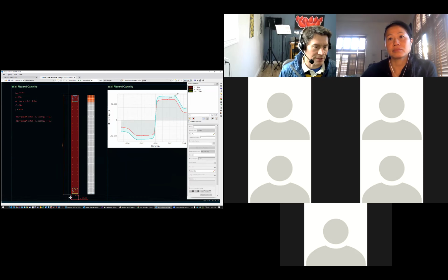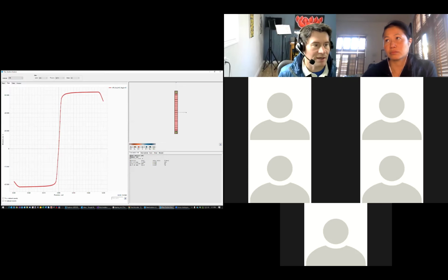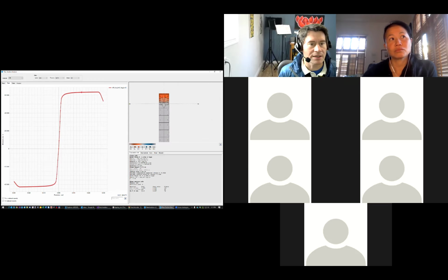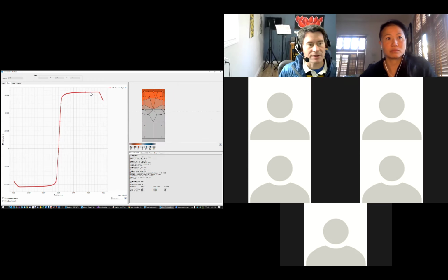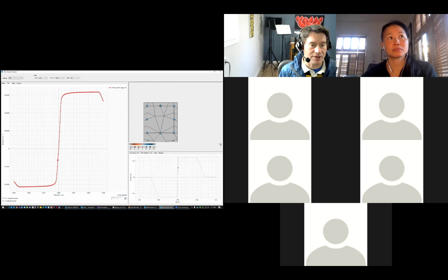And then we showed that you could do a moment curvature analysis of this wall, selecting everything here and typing MR, and it brings up the fiber section analysis form, and you can click on a point on the moment curvature diagram, and you can see how the cross section is behaving as you go along the moment curvature diagram. And then you can click on fibers, and you can see what the stresses in the fibers are as you go along the moment curvature diagram. I'm just pushing the arrow key as I go along here.